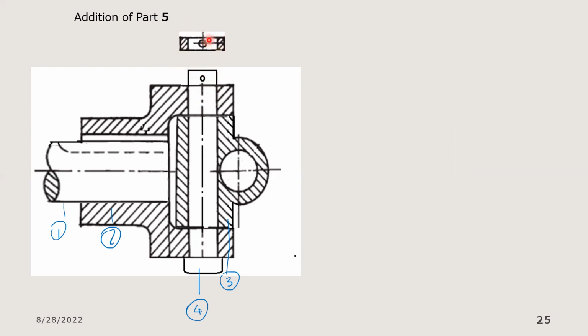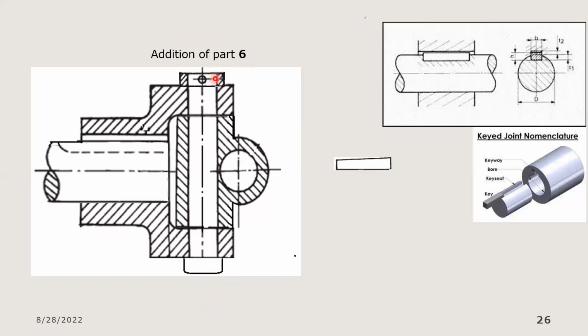And when you look at part 5, which is the collar, the hole through the collar also has a dimension of 16. So part 5 is the only reasonable part that should fit onto part 4. You are going to have part 5 here sitting on that.